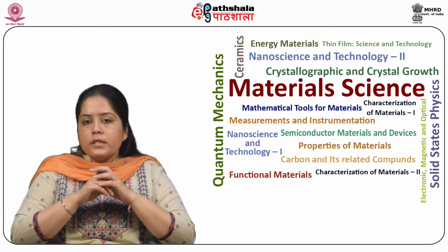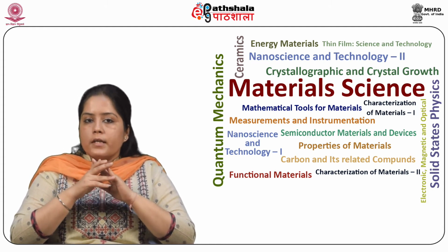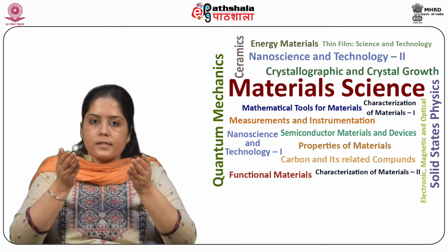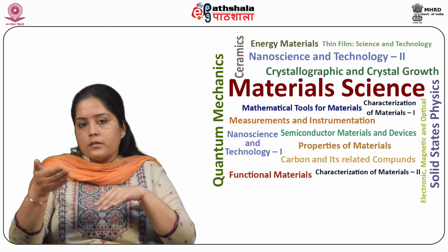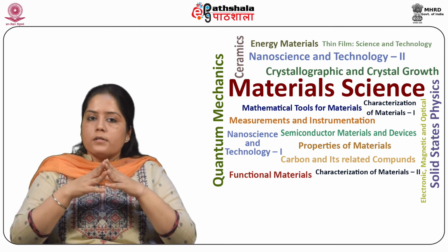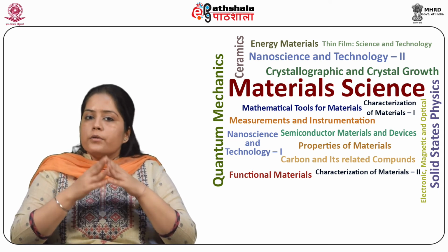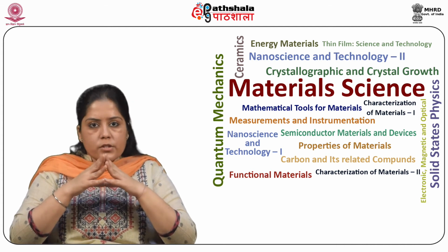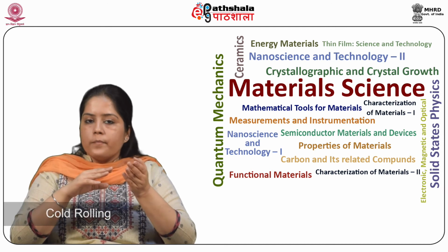The commercial iron silicon alloys typically have up to 3.2% silicon, as higher concentration usually causes brittleness during working operations such as cold rolling.